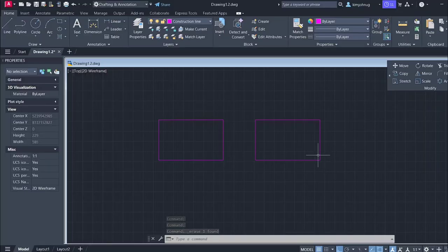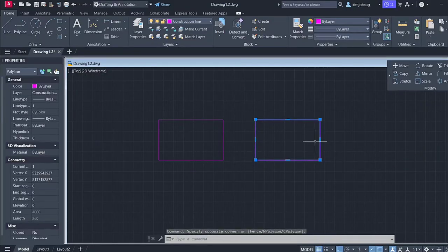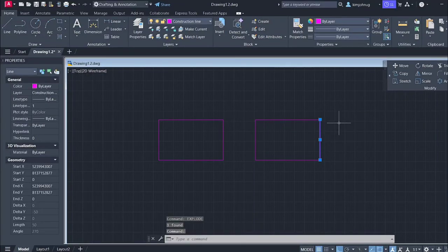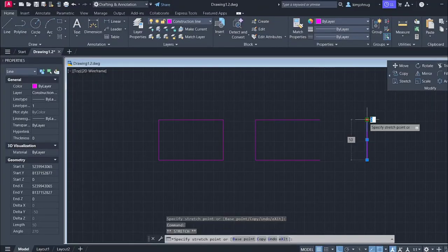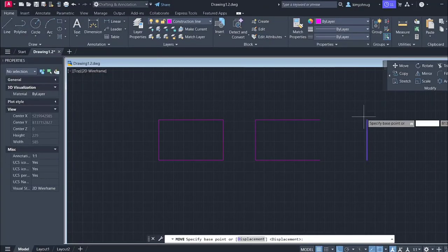The reason why I wanted to select this is because I wanted us to use the first tool. So I select this. I wanted to move a single line. I press X. Explode. Explode means separate. Separating a figure. So now I can move the line I wanted to move. You see this? The line I wanted to move. So you can also use the move tool.